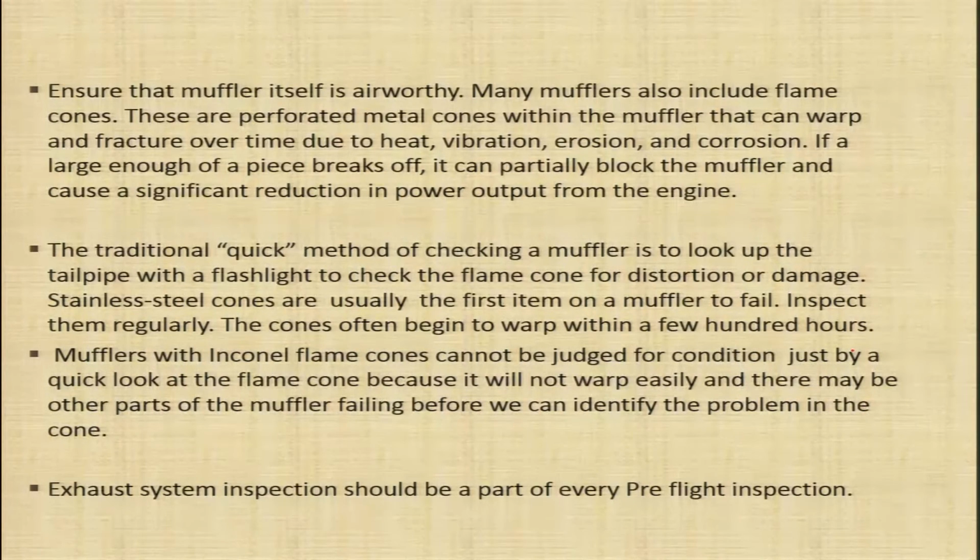from the engine. We all know that if there is an obstruction in the exhaust, it can result in loss of power from the engine. So if a large enough piece breaks off, it can partially block the muffler and cause a significant reduction in power output from the engine.